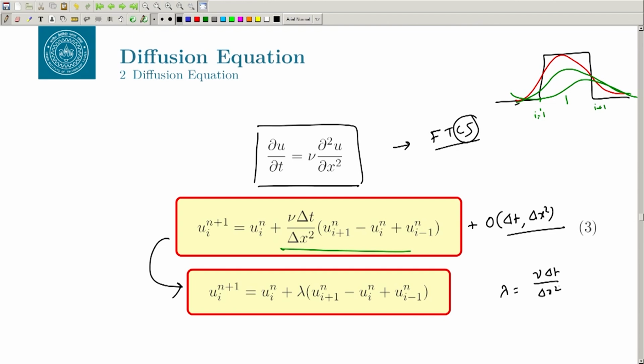Okay. So, now your diffusion will depend on your delta T, delta x, and your diffusion coefficient. In the fluid dynamics case, this is the viscosity. If you are using the thermal problem, this will be the thermal conductivity K, delta T, del 2 T by del x square, right. So, this lambda needs to be basically honored even in this case.